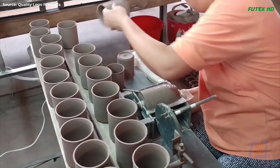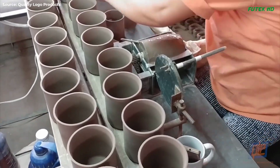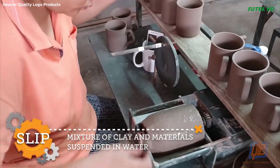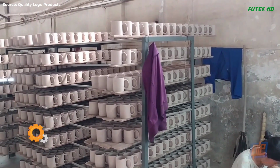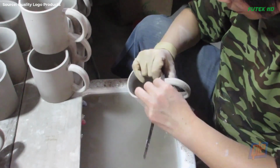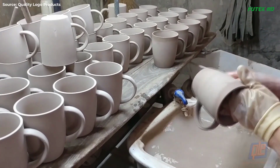Once the handles have dried and been released from their molds, they are dipped in a mixture of clay and water called slip. This slip acts as a glue to attach the handles to the mugs securely. Technicians carefully remove any excess clay or rough edges from the mugs, rinsing off any dust or debris to ensure a smooth finish. The mugs are then glazed to achieve their color and finish.